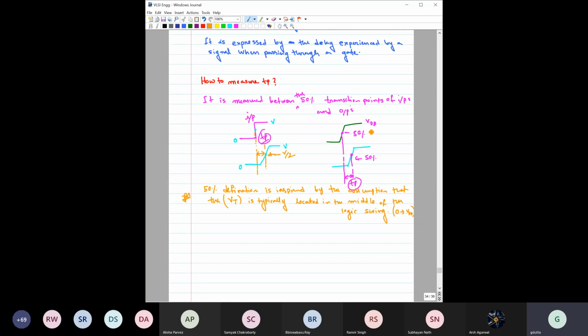So in the context of this digital IC, we would also like to have it like this. Suppose in case of this CMOS inverter, it is like this, right? When you are considering the charging of this output load capacitor, this output will charge from 0 to VDD, and while it is changing it should charge through this PMOS only, then this is off, and in that stage the input is like this, right?